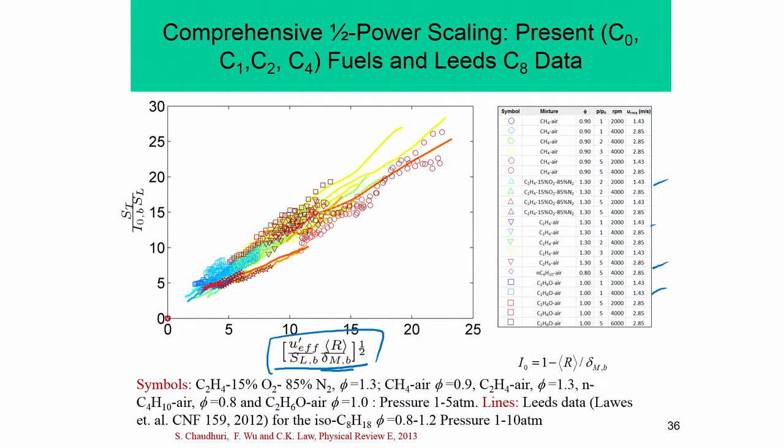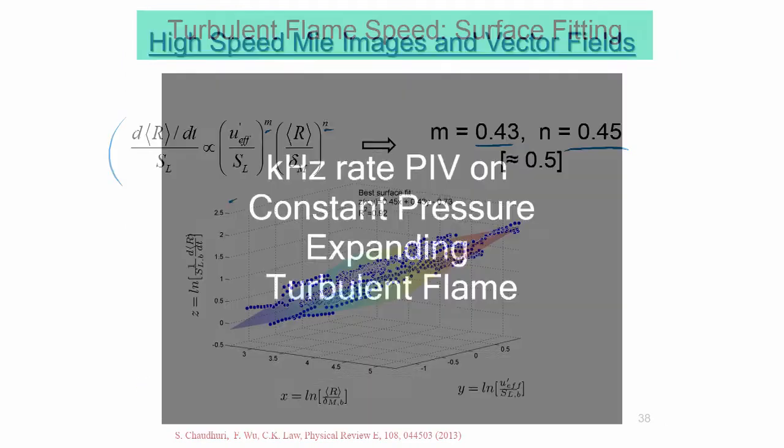create new area, should be considered, and for a kernel, for a spherical flame, only those turbulent structures which are of the order of the radius or smaller than the radius can affect the flame surface to create wrinkles, whereas turbulent structures which are much larger than the radius do not serve any purpose in terms of generating new area. So, that needs to be kept in mind, and that created these different scaling laws, and then we